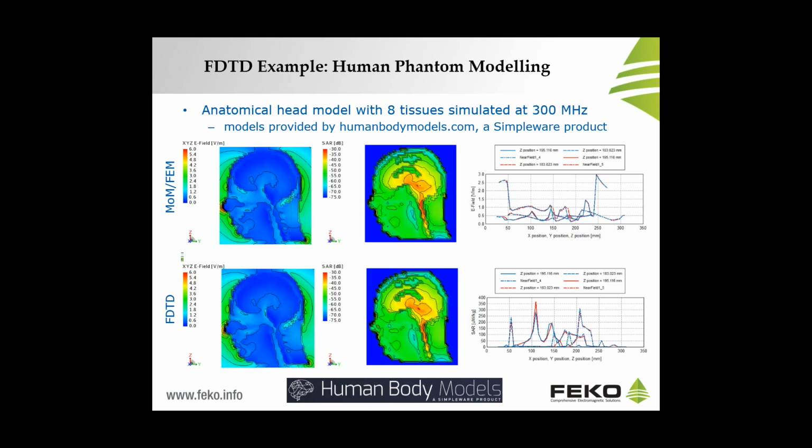And now with FEKO Suite 7.0 we can also solve inhomogeneous dielectrics with FDTD as well as with MLFMM, which again offers a clear advantage for the user to cross-validate simulated results for applications where obtaining measurements is complex and costly. Here you have an example using an anatomical head model with 8 tissues simulated at 300 MHz.